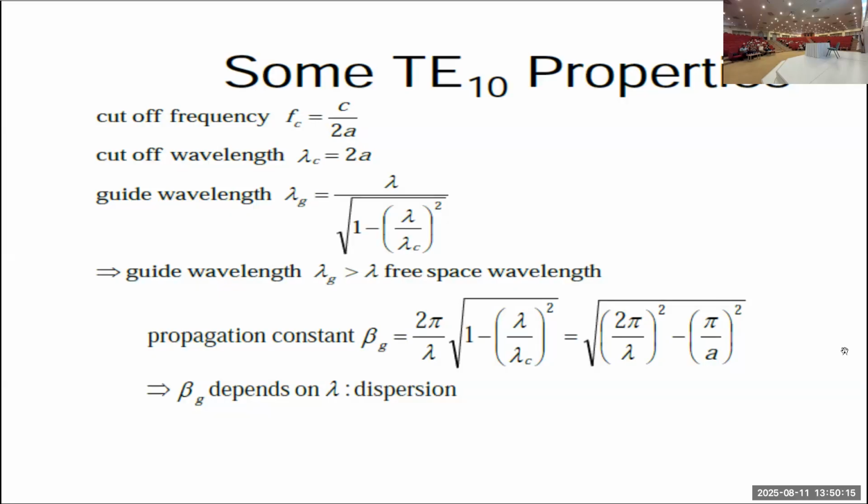So we can see that if we increase the frequency passing through the waveguide, the propagation constant decreases. The wavelength of the TE10 mode is maximum in this case, so its propagation constant is maximum. So the most efficient mode to transfer energy in waveguides is TE10.